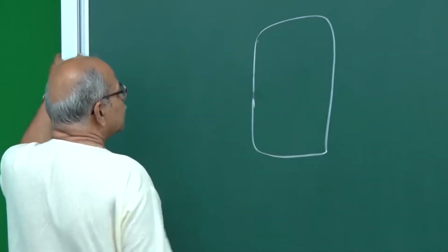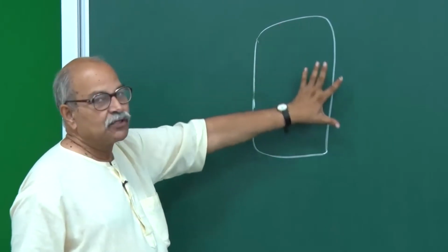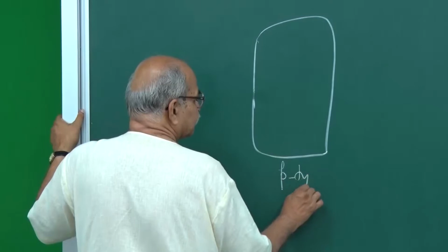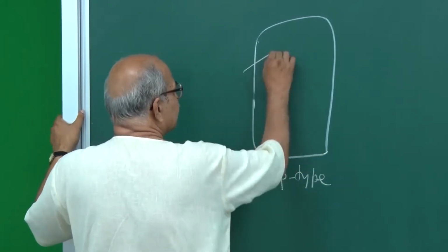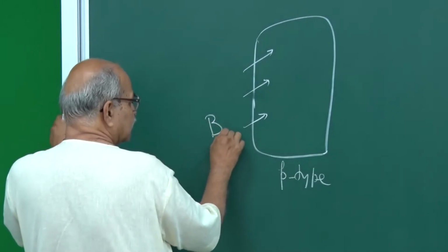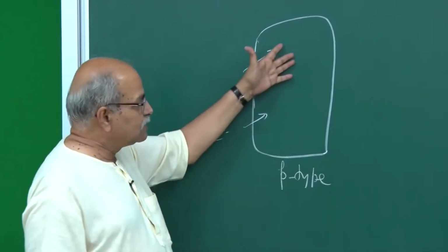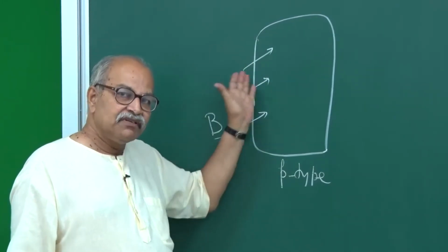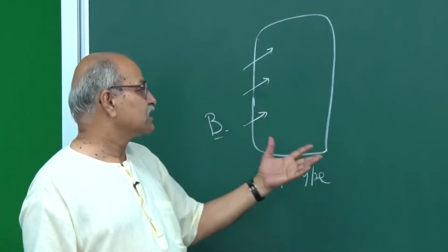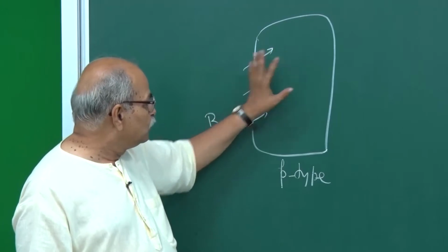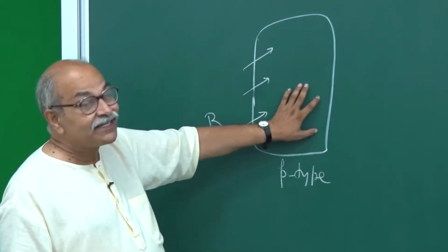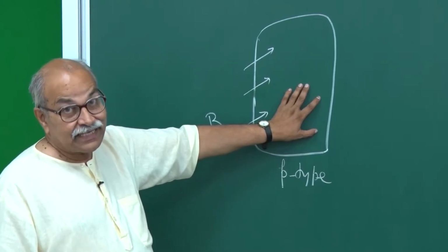So, that is the starting material, and with this starting material, the first thing is this entire wafer is made either p-type or n-type, this whole thing. So, let us say we make it p-type. To make it p-type, you have to diffuse trivalent impurity like boron. Here also you have very controlled processes. There are several processes by which you diffuse these impurities, and at the end you retain that silicon crystal.